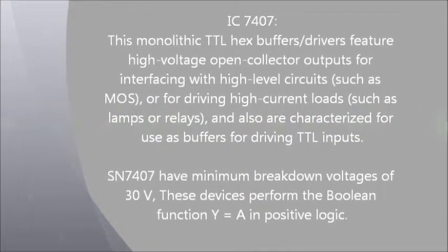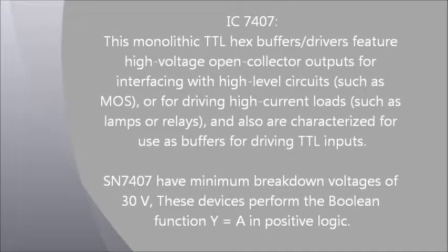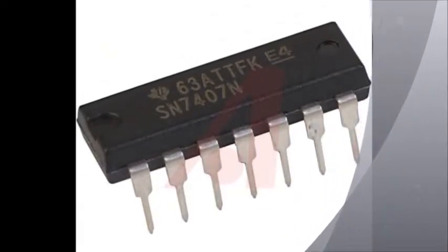IC 7407. This monolithic TTL hex buffer driver features high voltage, open collector outputs for interfacing with high-level circuits or for driving high current loads, and is also characterized for use as a buffer for driving TTL inputs. This is one of these.